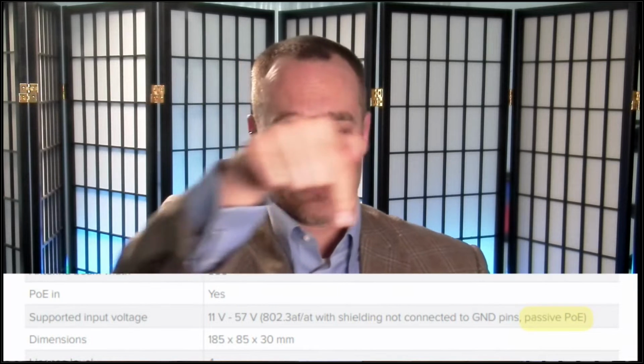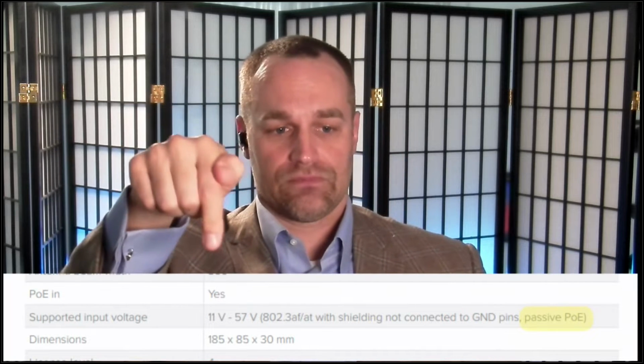Devices that are powered with IEEE standard PoE, often referred to as 802.3af or at, can, by standard, almost always power up on either mode A or mode B. They call that ambiguous. It's a way you design that into your piece of equipment that you can't do with passive PoE.